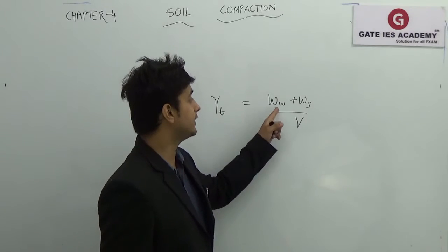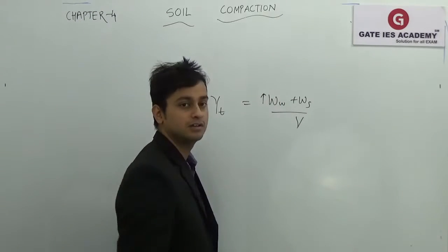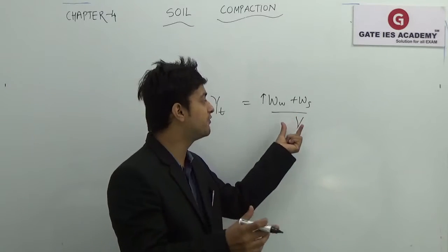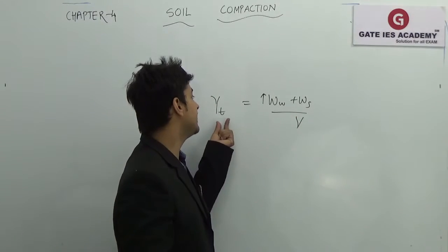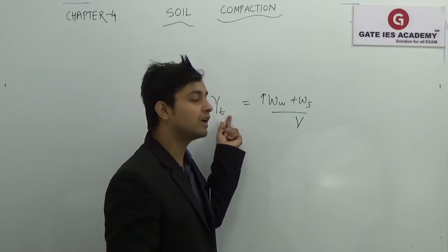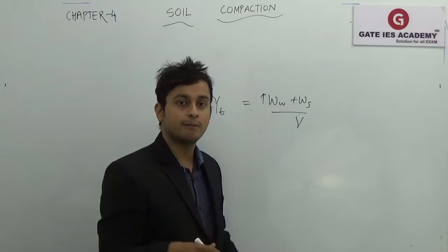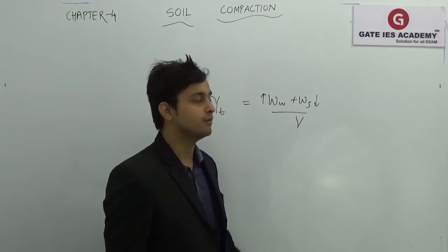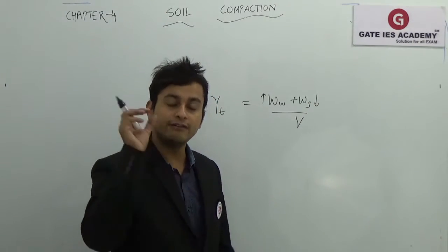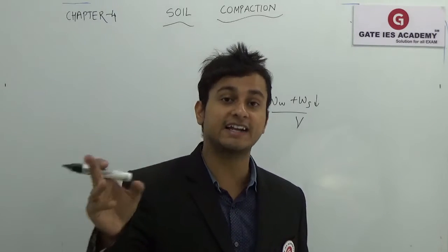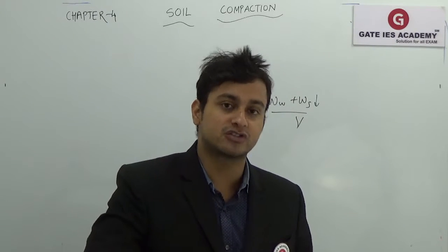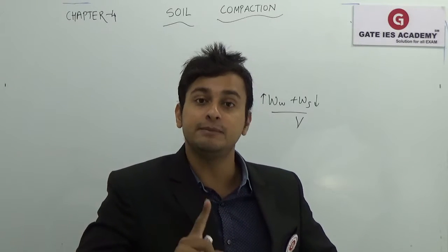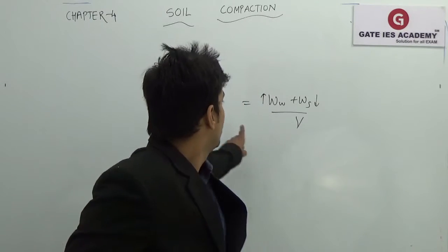If I check that, he can increase the weight of water, the water quantity, in that fixed volume, so that he can increase gamma t. So he'll put in more water and less soil solids. But if I want the embankment to stand still and take up loads, I need more soil solids. So he will cheat me in that regard if I check with gamma t.